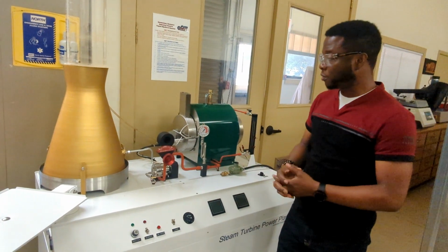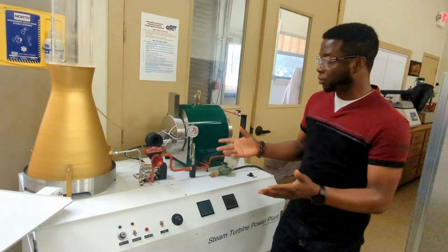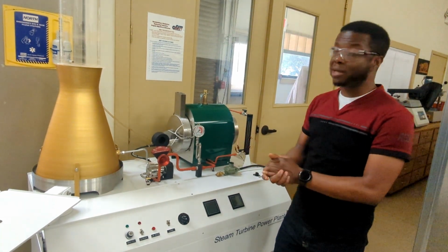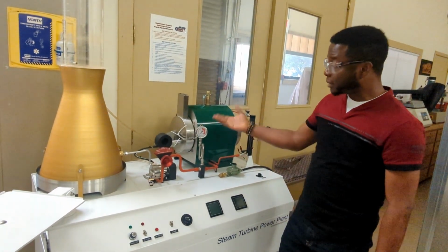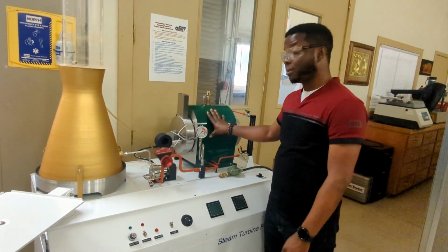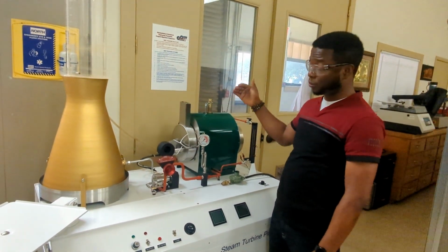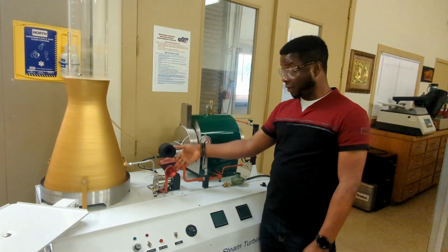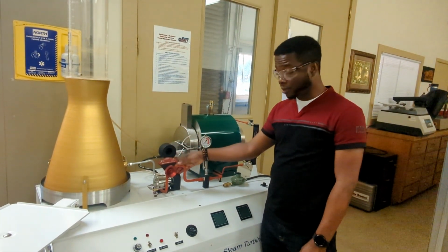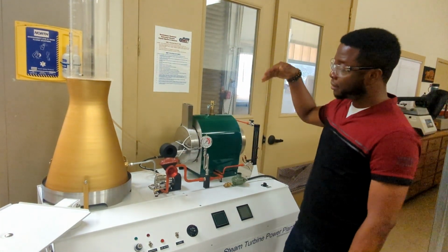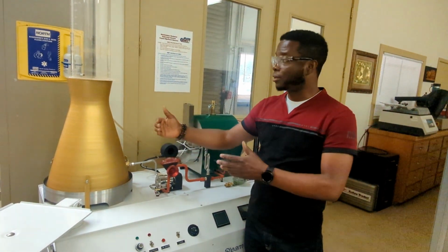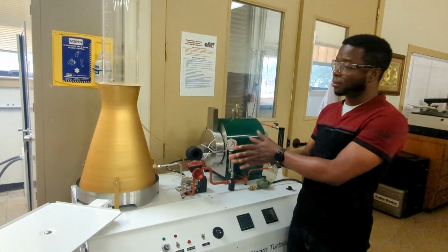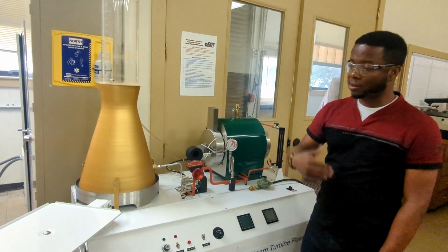At the end of these experiments, students are able to realize the processes of this Rankine cycle, from heated water in the boiler, steam coming off at elevated temperature to the turbine through the aid of the steam admission valve, gives power to the generator, takes up load, and the steam goes to the condenser, and the condenser takes off the hot water liquid and condenses it to low water liquid.